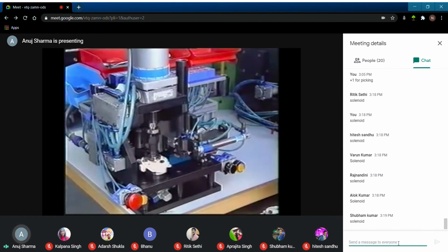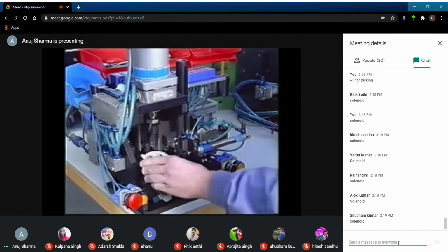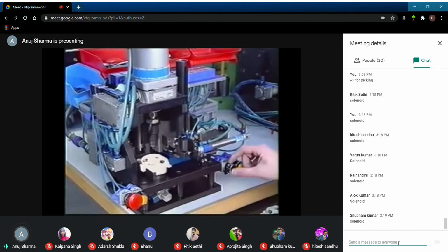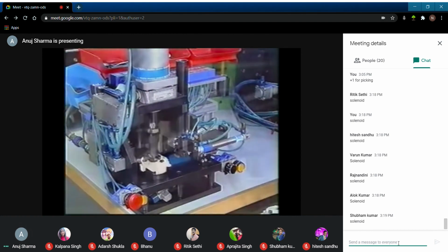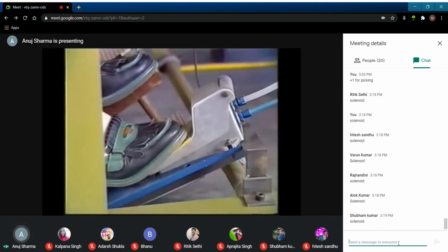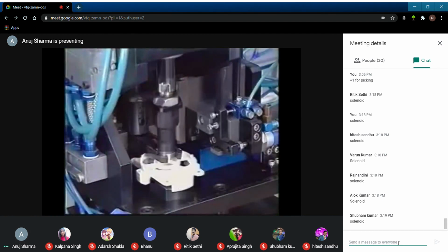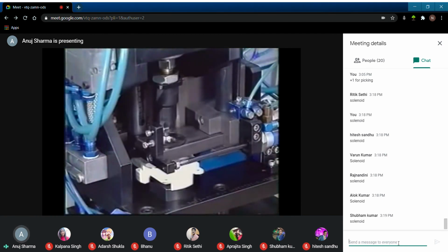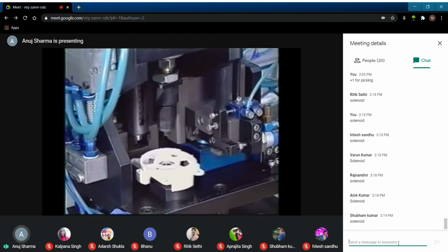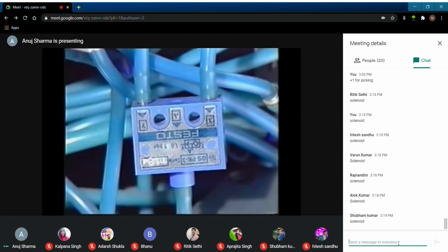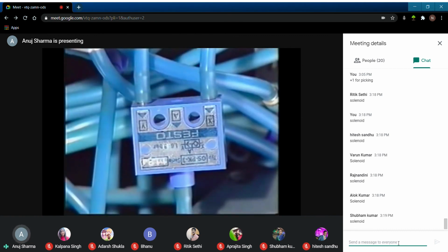A shuttle valve is used on this machine so that it can be started from either of 2 locations. The machine can be started by pressing a push button, or a foot pedal can be used to start the operation. The machine starts if a signal is received from either location. The 2 signals are connected together in this OR valve.